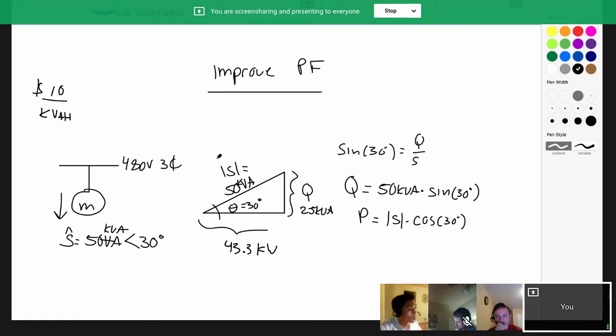For every dollar that we spend on that apparent power, we're getting an equivalent horsepower output compared to our kilowatts, right? We can use the kW to horsepower output. Horsepower is our mechanical energy. Kilowatt is our electrical energy. So we're buying our kVAs, and then it's the amount of kW that's actually doing any work, right? It's a fan ventilating a duct, an agitator motor mixing some kind of big slurry, or a conveyor motor.